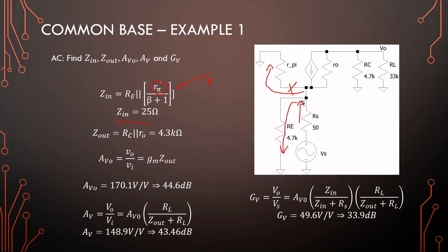And the transconductance, so this input here is extremely sensitive to temperature changes. So with these high frequency amplifiers, if it uses common base, it will typically have cooling to keep the temperature in check, because we don't have any form to stabilize the temperature right here like the previous problems. But you see we have a very low input impedance, so for matching with low impedances from sources, this is a very good amplifier.